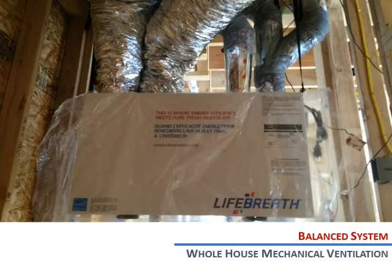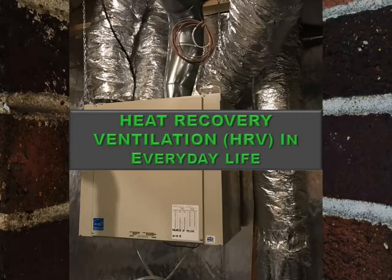The third is a balanced system, or as the code states, a combination of supply and exhaust systems. This is where you would have fans and ductwork that bring in outside air and an exhaust system to the outdoors. A truly balanced system would have the same CFM for supply and exhaust air, like an HRV or an ERV. Heat recovery ventilation, HRV, in everyday life.